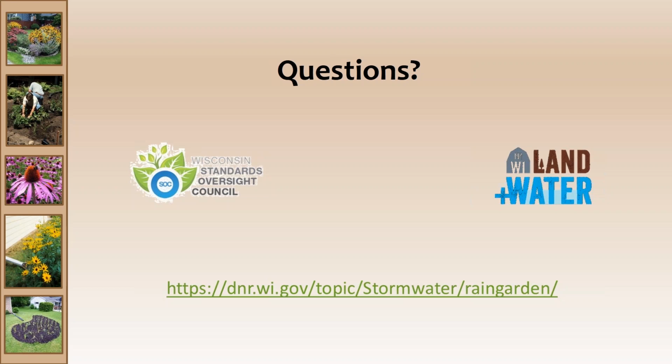If a rain garden clogs, does the standard specify how to fix it? And that's our last question. Yeah, I touched on it a little bit. If it's due to compaction, you can rototill some kind of organic matter or compost into it. That's probably your best bet. What do you think, Roger? Yeah, so the thought here is that the rain garden has failed and you want to sort of restore it. It depends why it failed, I don't know.